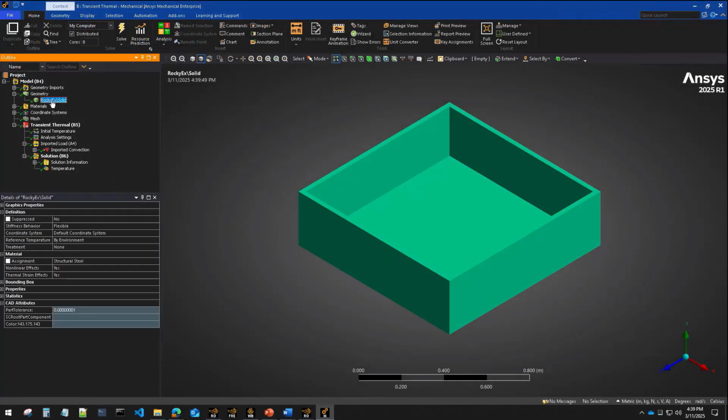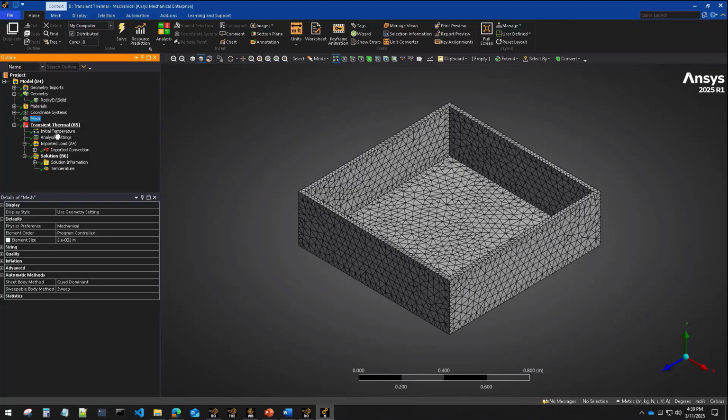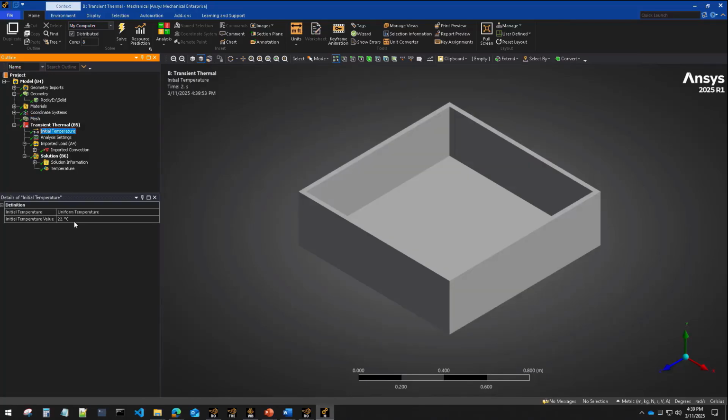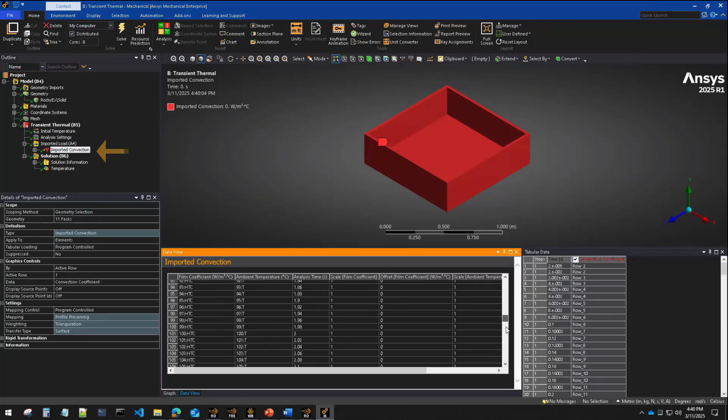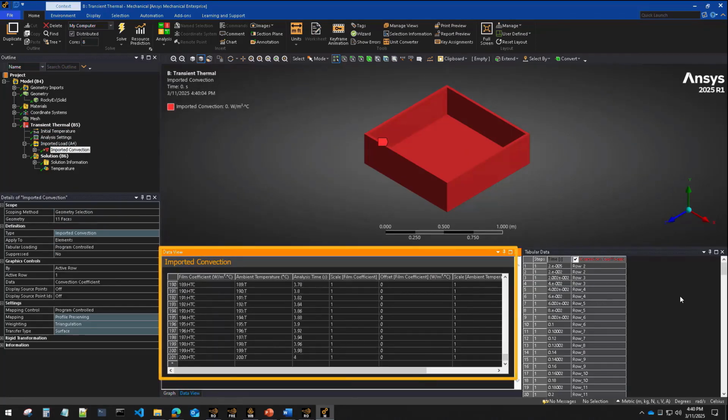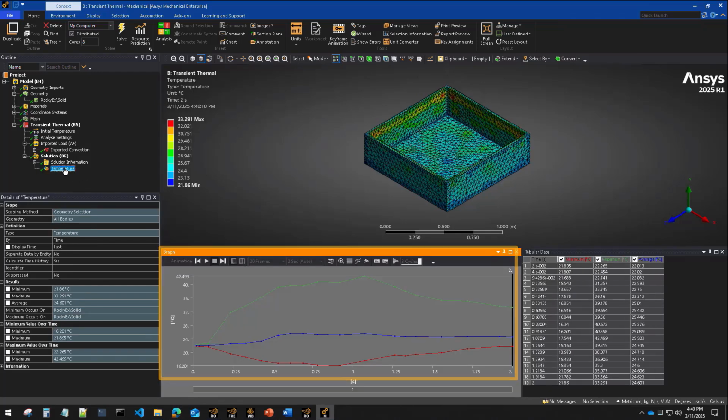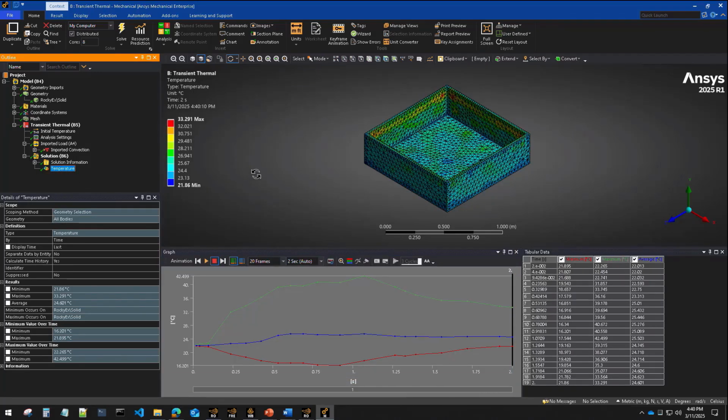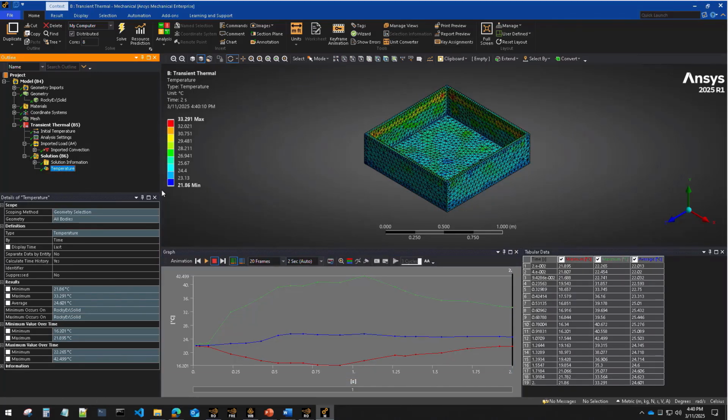After running the case in Rocky, the setup on the transient thermal side is the same as for the structural coupling, but the import load process will differ. The convection coefficient will need to be inserted, and the HTC data will automatically be imported as the forces data from the structural couplings. Then we'll need to set the faces for the HTC to be applied to. The temperature and other properties from the transient thermal capabilities can be post-processed inside Mechanical.